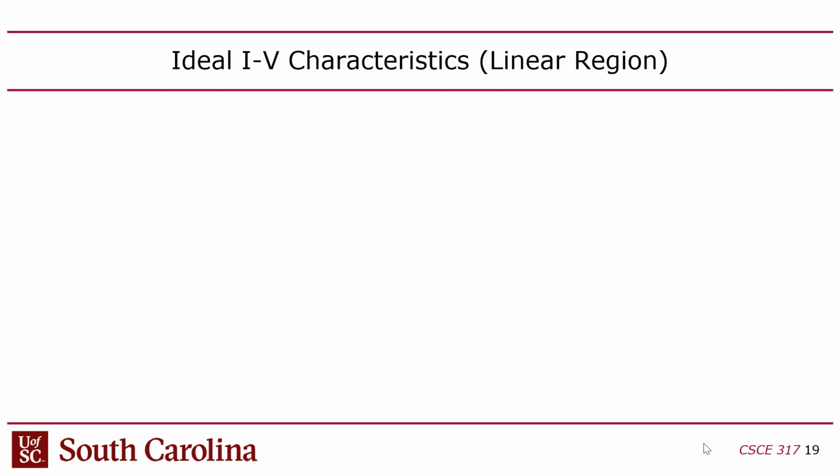It's an analog voltage, so as long as you're above the threshold but below VDD, you'll get different behavior out of that transistor in terms of when it saturates.